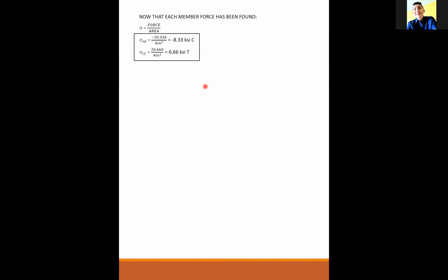The question that was written is why we need the sign when we mention it is in compression. It kind of reinforces each other. In these types of problems, I'm not sure how you were taught this in statics, but basically the negative sign is there to tell you that when you assumed tension, it's not tension.